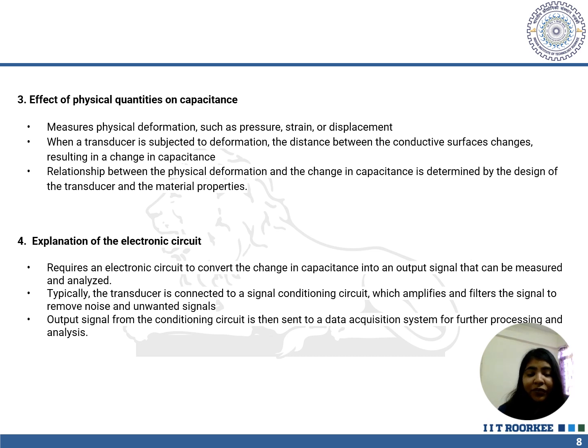And there is also an effect of physical quantities on capacitance. Various physical deformations may occur because of pressure, strain or displacement. The relationship between the physical deformation and the change in capacitance is determined by the design of the transducer and the material properties that we are using for the plates and the dielectric material.